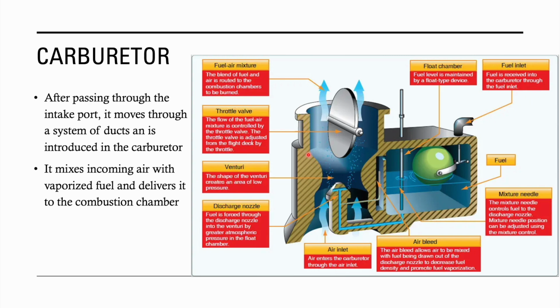And going back to aerodynamics, as air passes through this venturi, which is kind of this narrow section right here, the air velocity increases, which decreases the air pressure at this location. So right here, you have really low air pressure because it's going faster. So that change in pressure, now you have higher pressure inside the chamber, lower pressure here. Pressure wants to go from high to low, so it's going to push fuel from here and vaporize it in this throat right here.